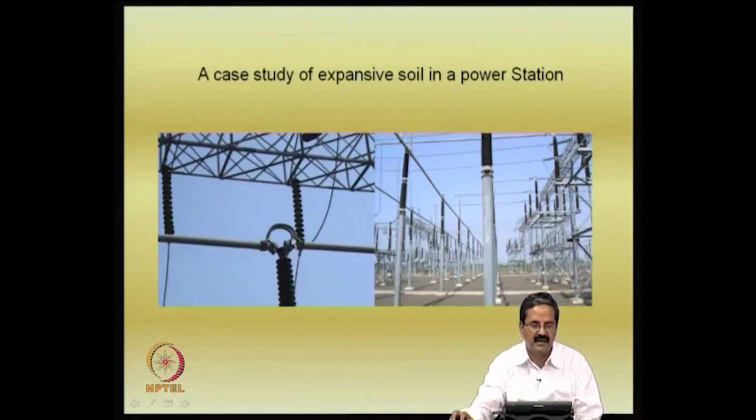It is out of line, they have to be in line actually, all the electrical things have a lot of tolerances, and if you have an expansive soil, the problem with expansive soil is that it heaves and then shrinks, right. So the possibility is that it could cause total settlements as well as differential settlements, and in this case the problem is tilt, the pole should not be tilted away with respect to something. And the thing is what type of foundation they have, they will not have any major foundation, right.